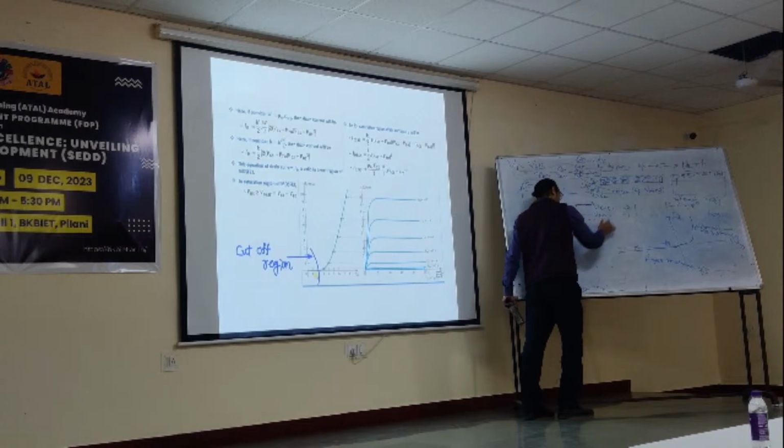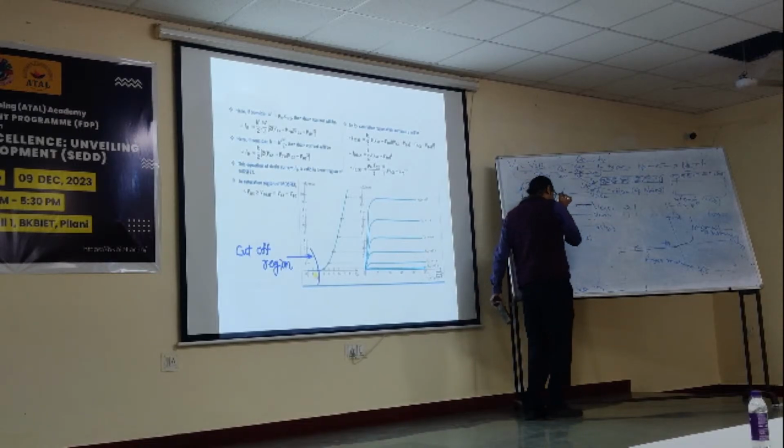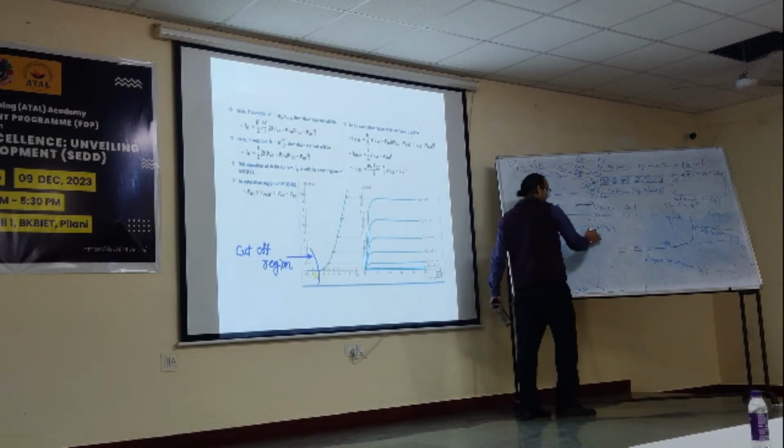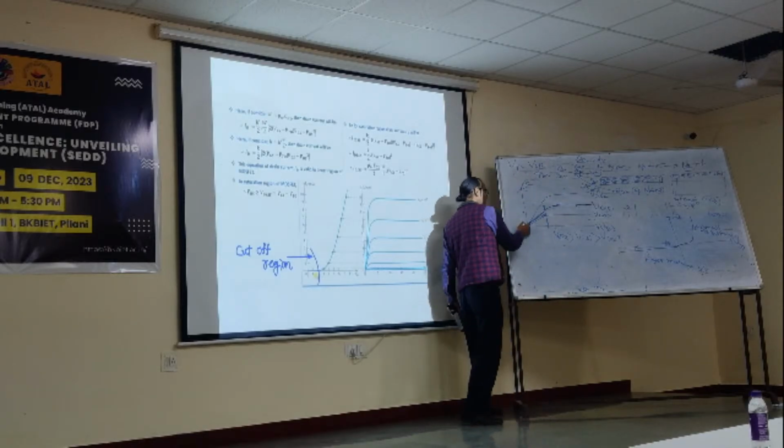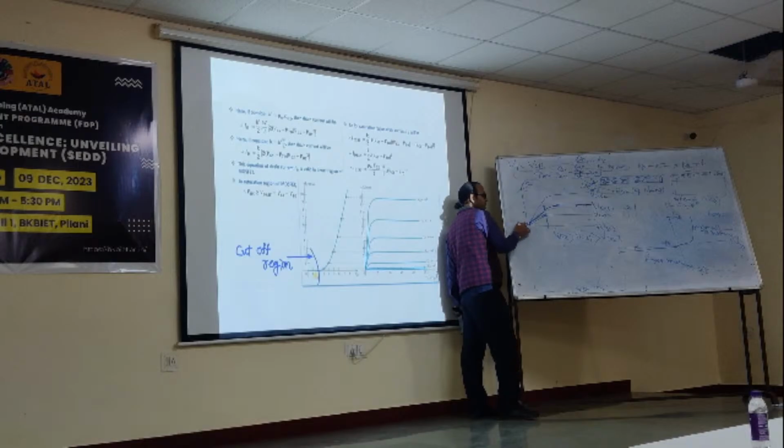If I decrease it, then VGS2 is more than that, and VGS3 is less than that. Okay. Now, if I want to plot the reverse, ID versus VGS, because ultimately the drain current is the same, I can produce these lines backwards. That is what is done in that picture, right? And I will get a graph something like this.